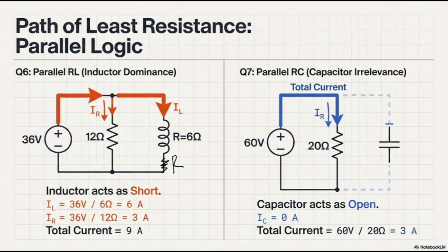On the other hand, we do have the path of least resistance. What does that mean? Imagine that you do have the power resistor with what? We do have the R and L. We do have another R, and we do have the 36 volts. So what would happen after infinite time? It means that while your inductor is getting fully charged, this guy is going to act as a normal wire.